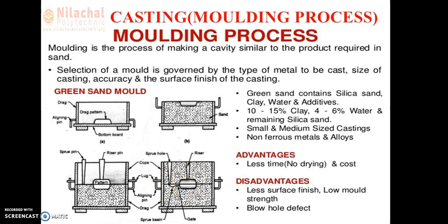So let us discuss the next method, that is known as pit molding. Very big castings which cannot be made in a flask are molded in a pit drag on the floor. Very large jobs can be handled and cast easily through pit molding. The mold has its drag part in the pit and a separate cope is rammed and used above the pit drag.